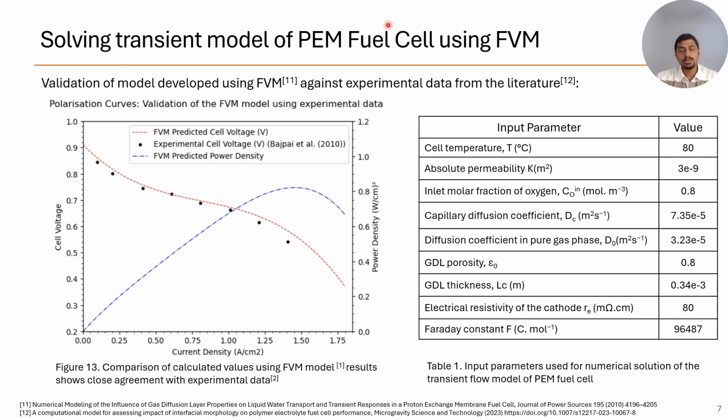The model was developed using FEM, and that was compared against the experiment data from literature. You can see that the experimental data closely matches the FEM predicted cell voltage, except for the last 2 points where you have a slight deviation that is attributed to multi-phase effects. Here, only single phase of liquid water was considered. This is the table which shows input parameters used for calculation of the numerical solution.